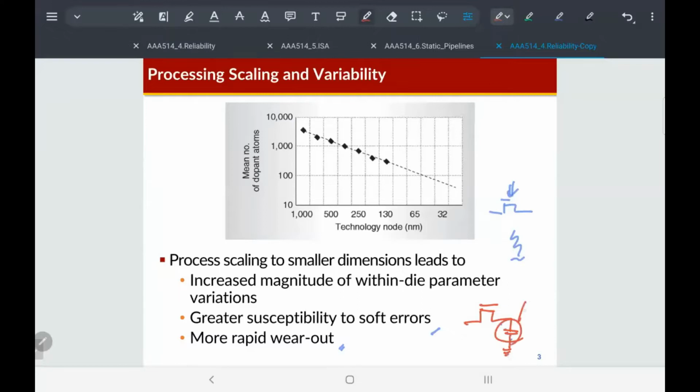The data of the DRAM is stored in a capacitor. If the DRAM size is reduced, then the amount of charge stored in this capacitor also decreases. Which means that the data inside modern DRAM devices is more susceptible to soft errors because the charges can be changed. It is also true for modern memory devices such as flash memory. So the reliability issue is very critical for flash memory.